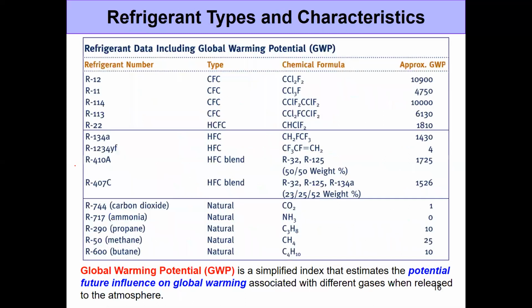All right, so now let's just look at the listing of different refrigerants which have been used throughout history. And there are a couple of things that you want to ensure. First thing is you want to ensure that the global warming potential is as small as possible. Okay, for CO2 it is 1, and you would want to keep it as low as possible, right? Because it just causes global warming. The other thing is we want to try and avoid CFCs as much as possible because these damage the ozone layer. Okay, so these have been ruled out in a lot of countries. There are still some old refrigeration systems using them, but they will be out of operation in a few years' time, if not already out of operation.